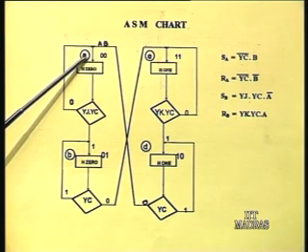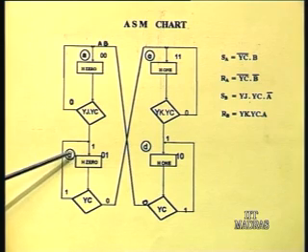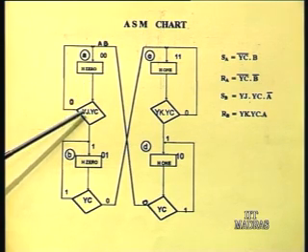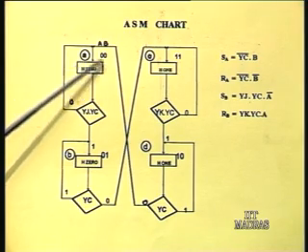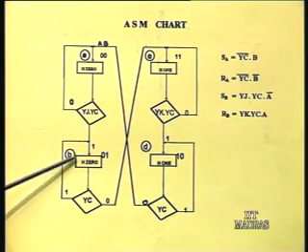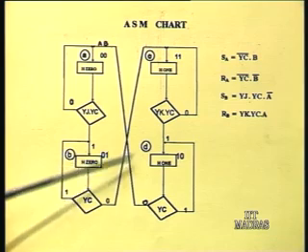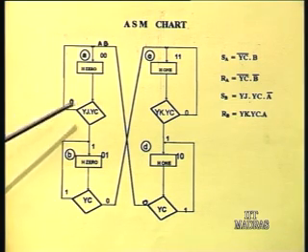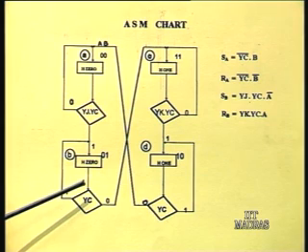With A as present state, the two possible next states are A itself or B, the inputs to be checked are yj and yc, and the output to be generated is H0. So, this is for one state. Like this we also do for the other 3 states. So, essentially we had 4 such microwords, right. These 4 microwords we put in a read only memory and got the firmware design.